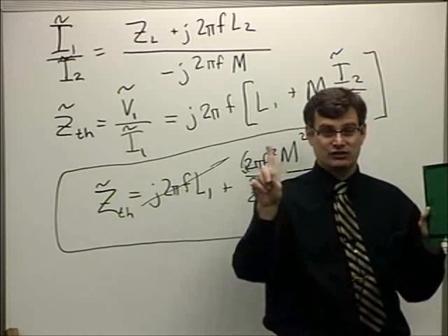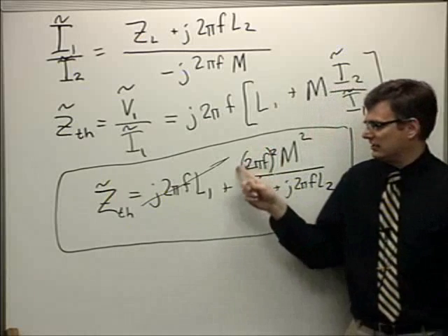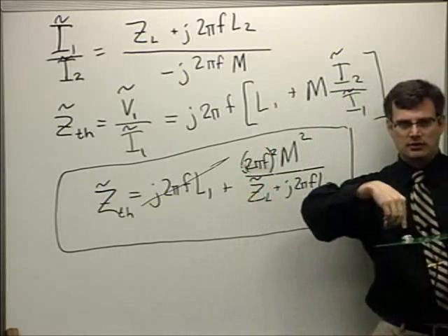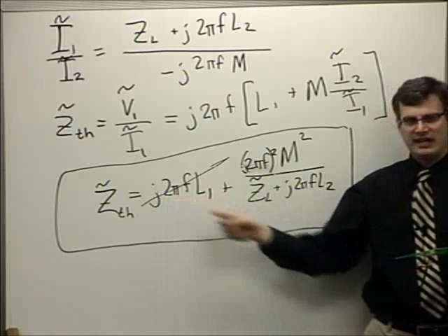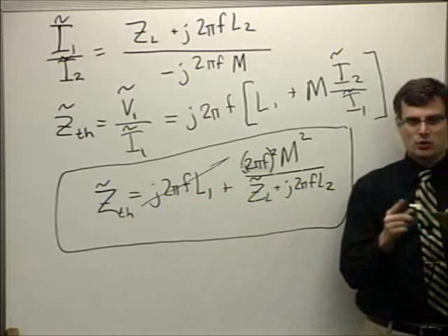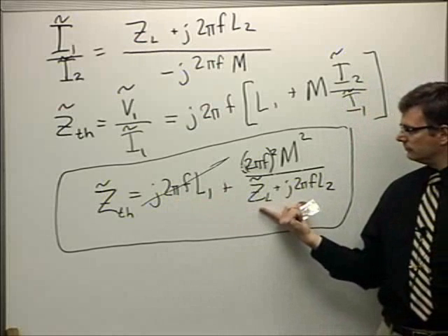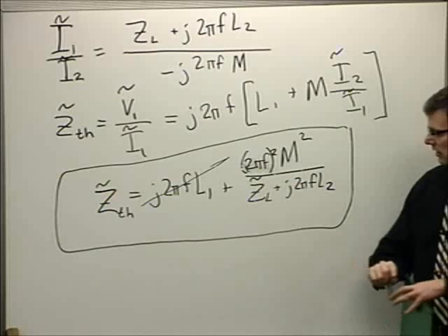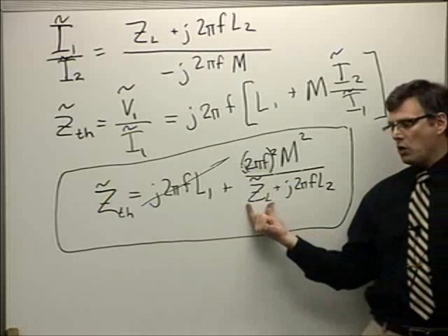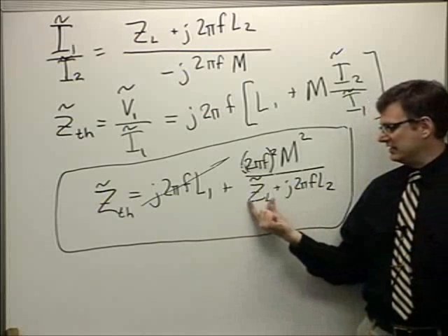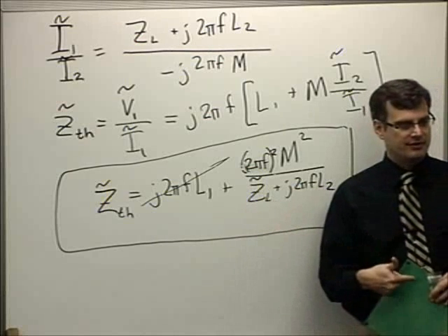But it has to resonate. And that gets us back to the second term here. So we put a nice capacitor. We tune it so that we cancel out this term. Now the Thevenin equivalent at that port is only due to this term. Depending on what I load my coil with here, this is the impedance of whatever chip that I splice in.